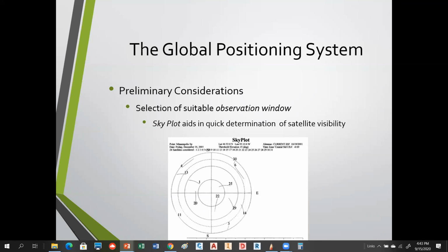Absolutely. So you definitely can, like you said, you can kick them out, right? Yeah, at least with the Trimble collectors, you can go in and turn individual satellites off, or you can just increase the elevation mask. Right. Increasing the mask is easy, and I think both things you said are pretty easy, and I think that's pretty standard on most of them nowadays. As far as I know.